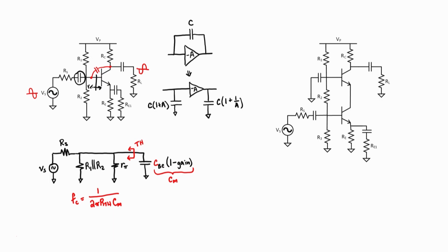Over here on the right, we have a cascode. This is going to largely solve the problem. We're actually still going to have the same base to collector capacitance here on the right as we did on the left. But the situation is going to be mitigated because I'm going to design this common emitter amplifier to have a lower absolute gain.